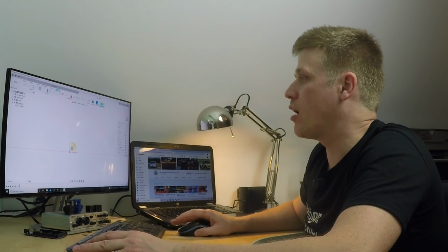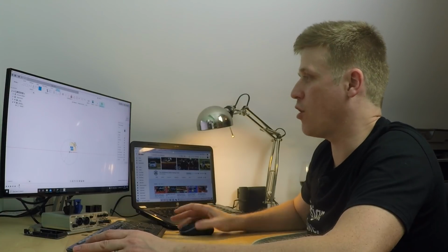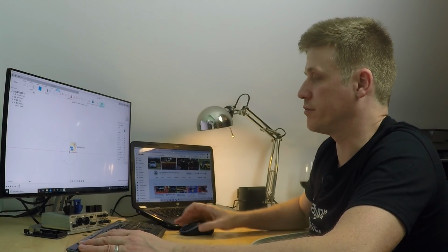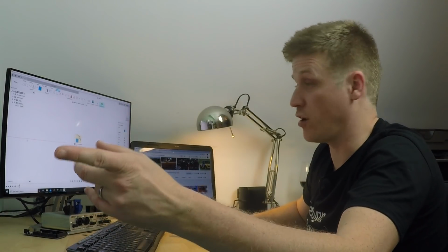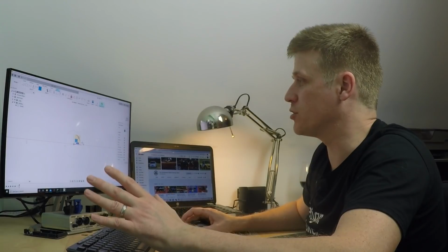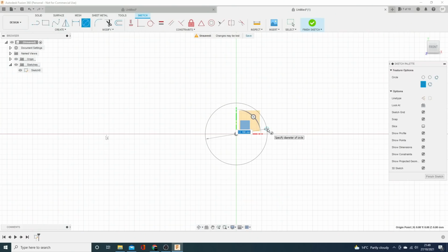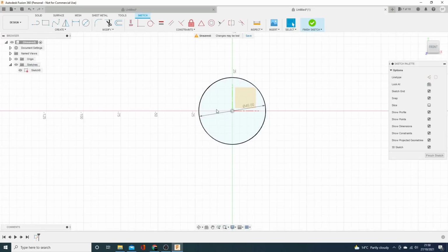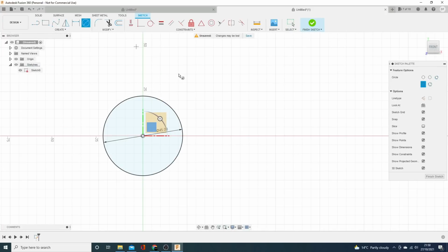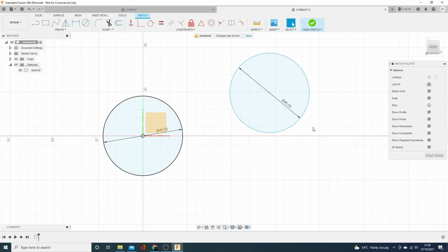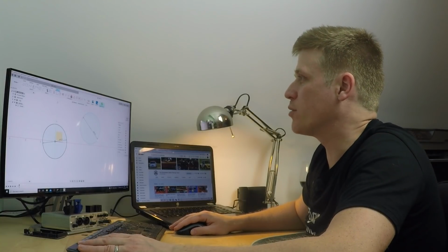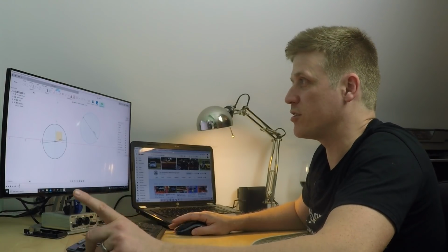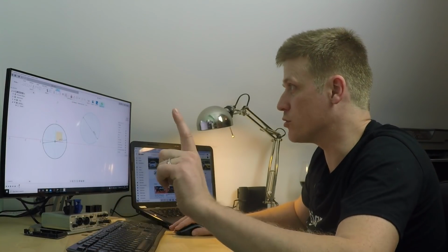So I know for sure I've got a drawing, and I've got a drawing kind of over there. So I know my key dimensions, and my first key dimension are the induction holes, which are 45 millimeters in diameter, and they are 80 millimeters apart. So 45 again in diameter. Now I'm going to constrain these and put some effort into constraining them because they are important to me.